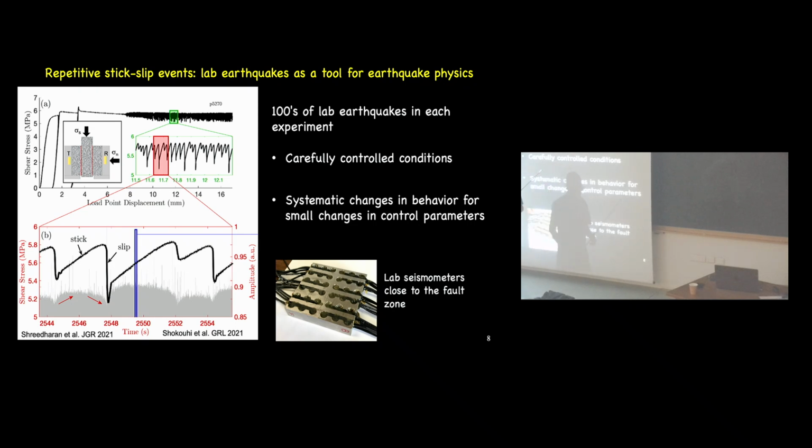It's useful to cycle the load, the shear load. This generates a mature fabric, generates the fabric more quickly. And I'll talk about the variations in that fabric and behavior as a function of shear displacement. Or we could talk about shear strain within the fault zone.